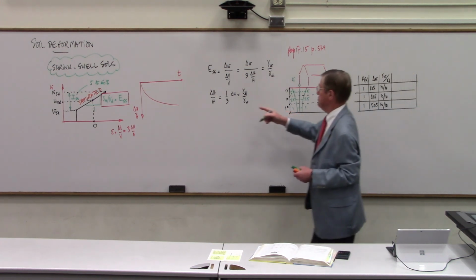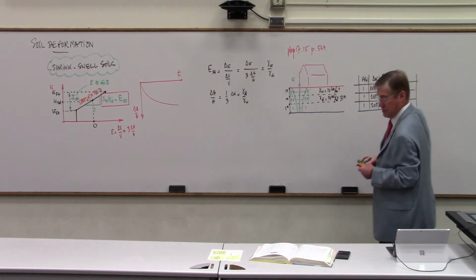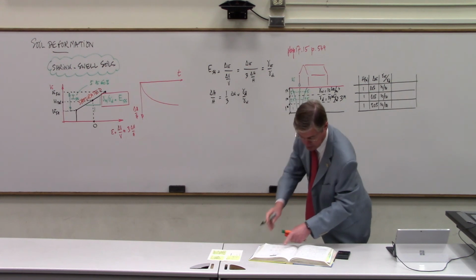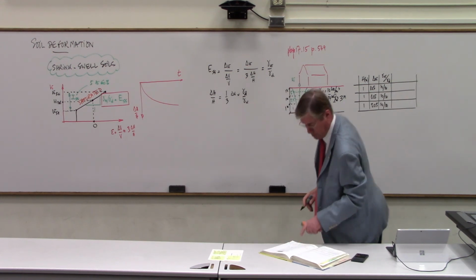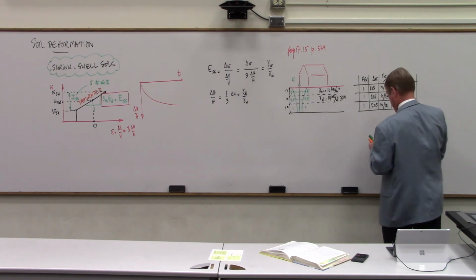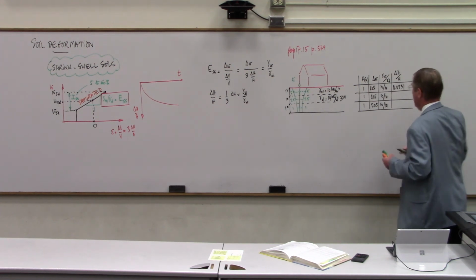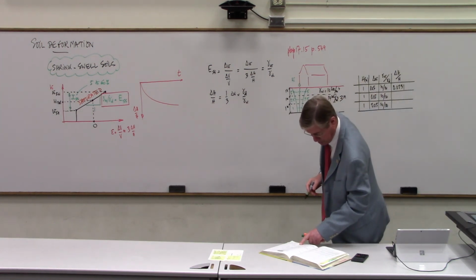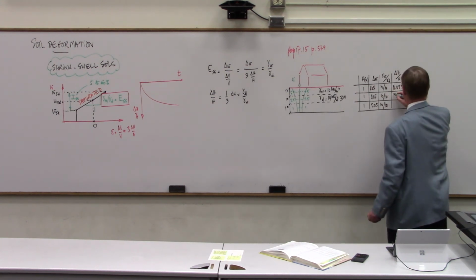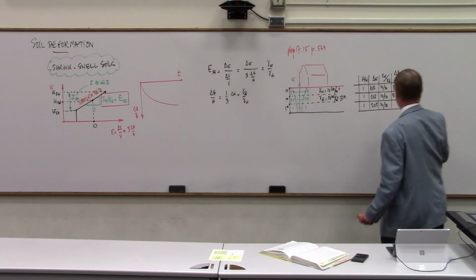And then I'm going to do 1/3 delta W to get delta H over H. And so I got 0.0231, so that's delta H over H. So I'm going to have to push over a bit. For the second layer, I've got 0.01155. And the third layer, I have 0.00462.